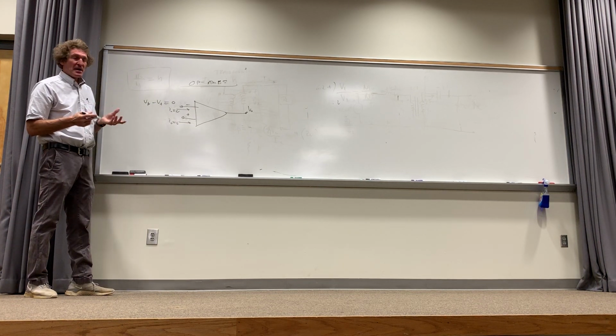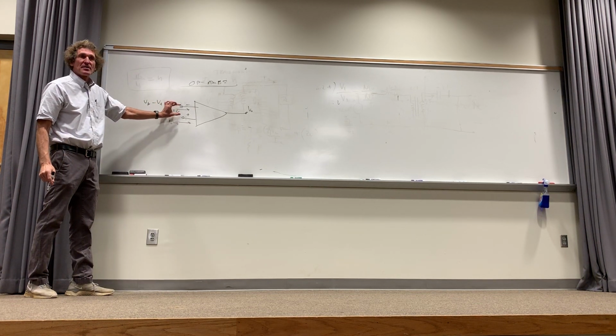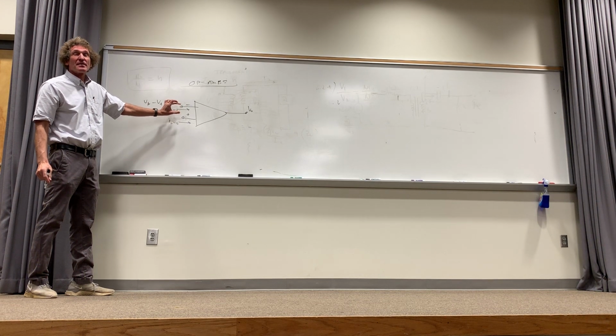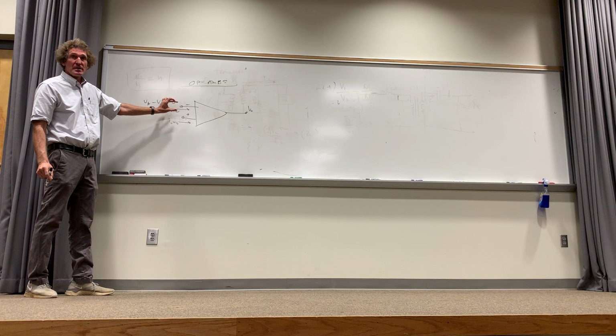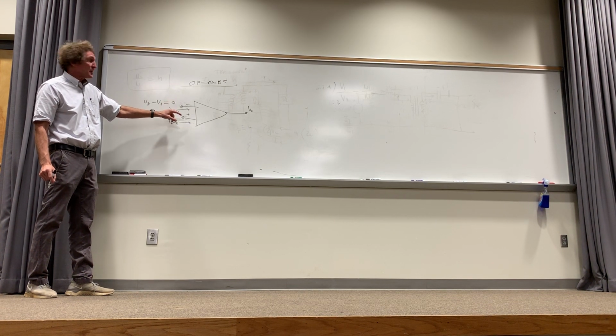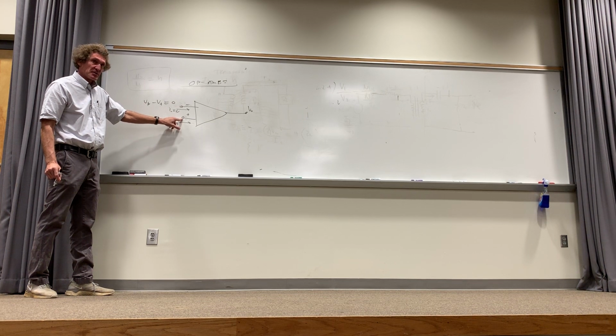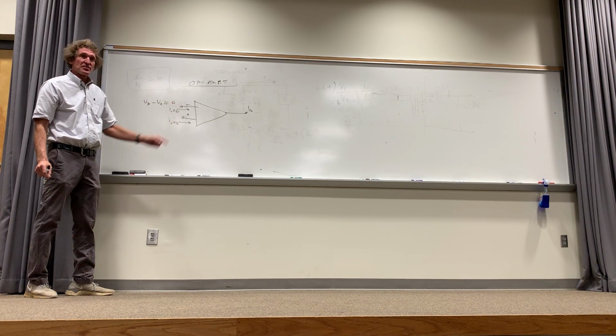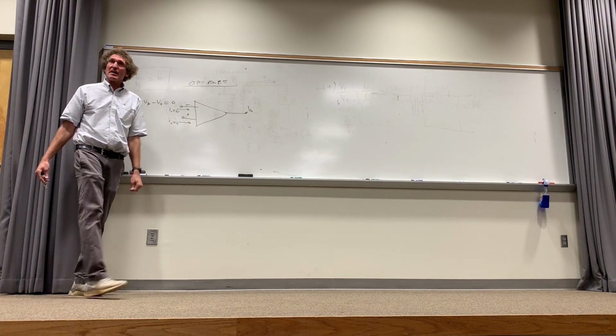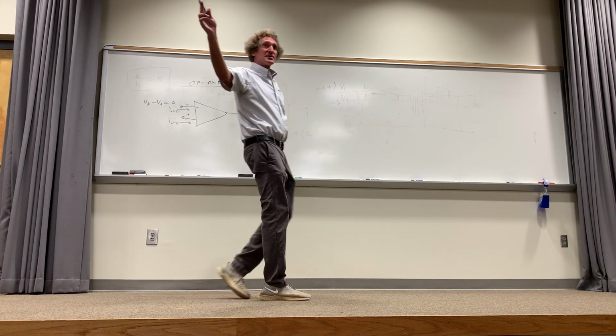How can that be? I can take a battery and put it across there and I have a voltage, right? Well, the fact of the matter is if you did that, this operational amplifier would not be working in a linear region. What it does when it works in a linear region is prevent any appreciable voltage difference between these two, and no current flows into it. Now, how does that work to amplify things? I'm glad you asked. Watch and you'll see.